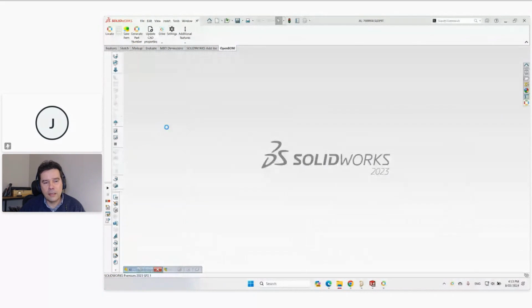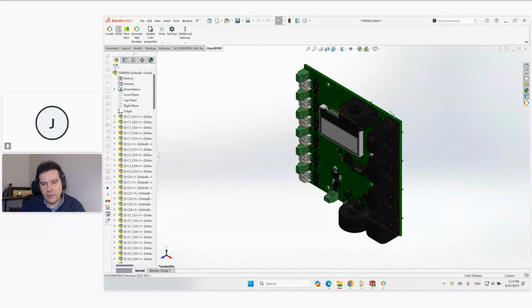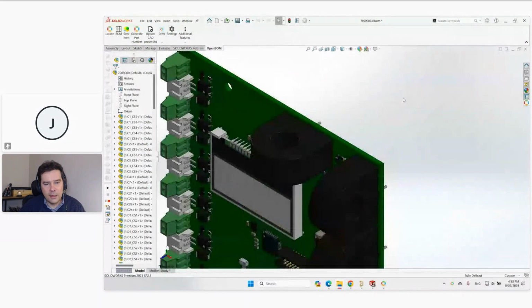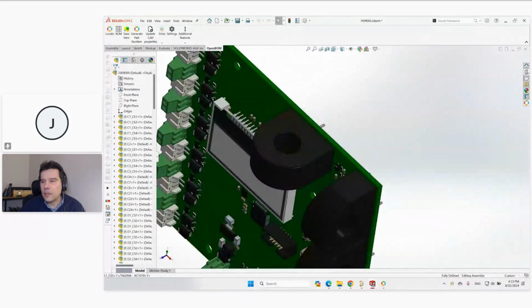If you extract the Parasolid from Altium, you basically will have too much detail. It looks beautiful, and some of us love this sort of 3D, but it's actually very slow, and it creates a lot of sub-assemblies which you don't need for this point.